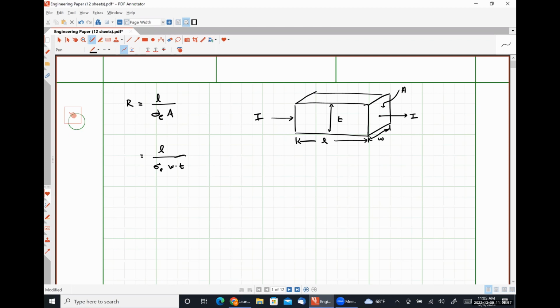Okay. So what is interesting about the resistors that we are going to be dealing with is that they will typically be of some fixed thickness. What I mean by that is we are going to form resistors by either performing a diffusion doping process or an ion implantation process, and we are going to define our resistors in one fabrication pass.